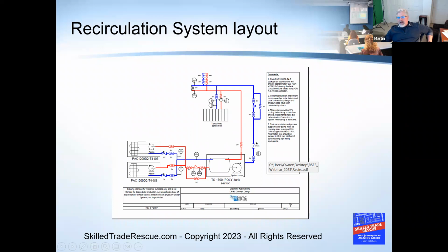So this hot line right here, or the delta T between the two lines, I'm just going to pull some numbers out of my hat, but let's say this is going in at 45, and before they did whatever they did on that load, we only had maybe 47 going back, right? Depending on the flow rate, but low load. And let's say whatever it is they're cooling, they turn that sucker on, and bang, all this hot energy comes in on the hot side of this heat exchanger, and this 45 is feeding, and all of a sudden this thing jumps up to 60, right?